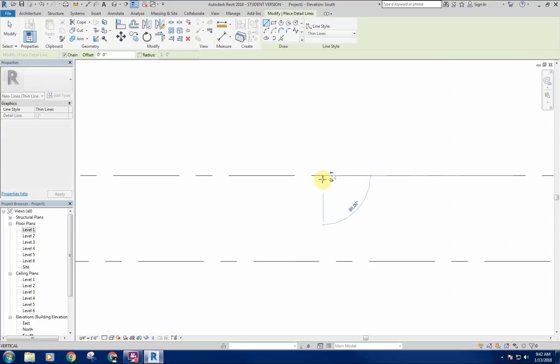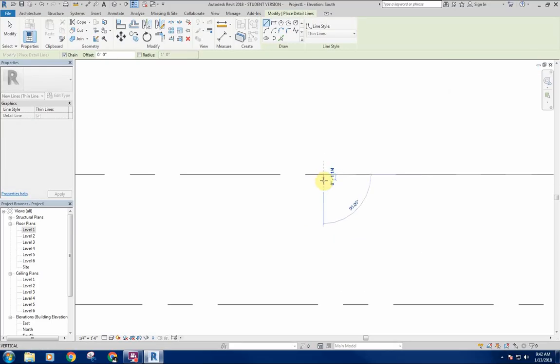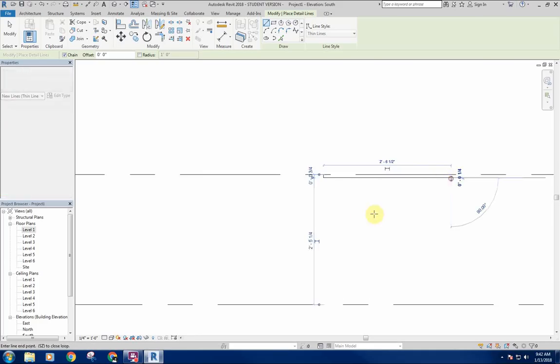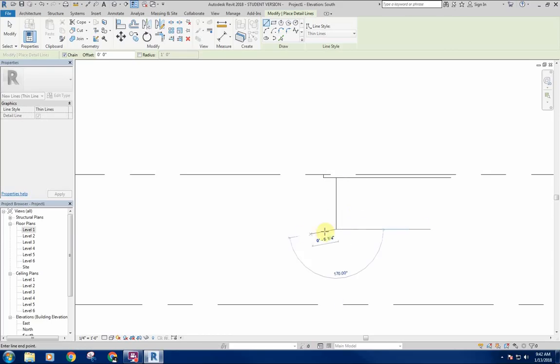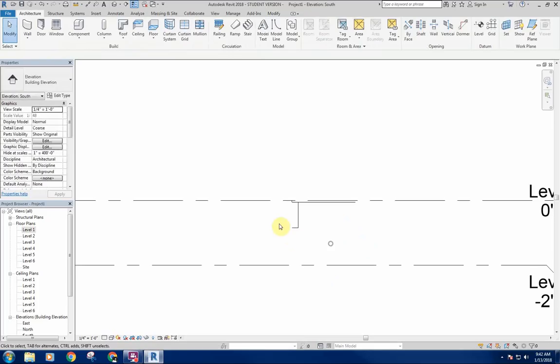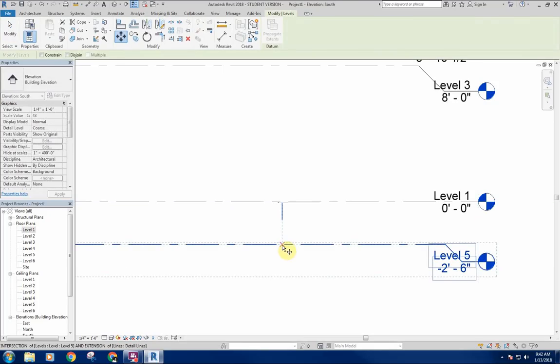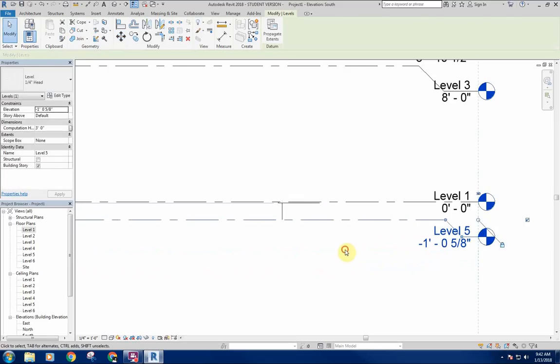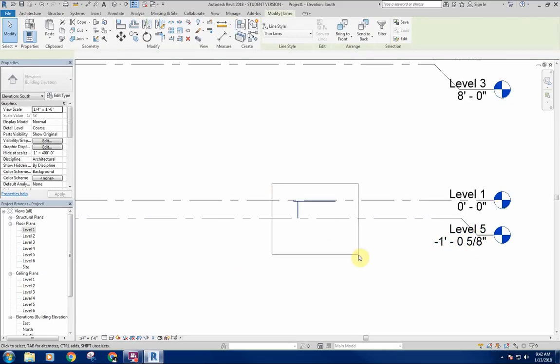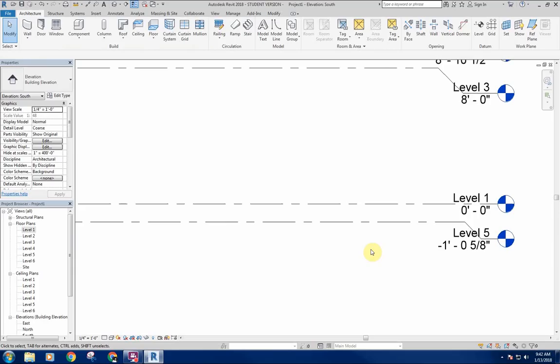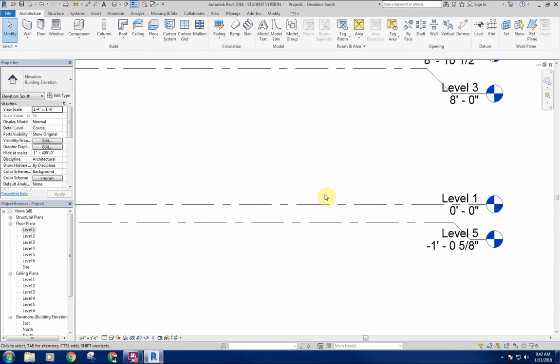So if we've got our 3/4 subfloor, we'll probably have something like an 11 7/8 floor system, and then there's nothing underneath that because it's just a crawl space. So if we move this up, so now I'm down 1 foot 0 5/8, which should work just fine.